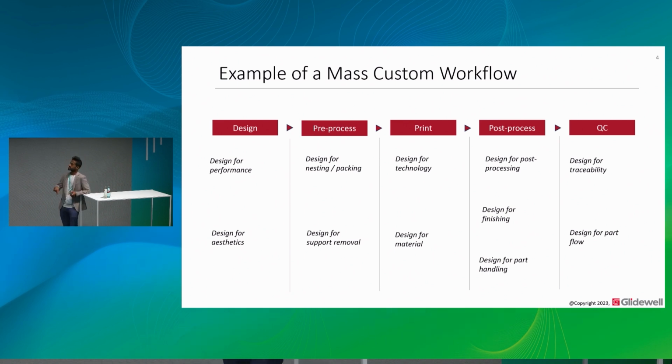So that means there's a separate finishing or polishing step that usually a skilled technician is going to do. They're going to have to eyeball things, and they've been trained over years and years. And there are design elements that we add for both of those separately that help improve that. So we're actually fine with increasing print time if it helps reduce finishing or post-processing time. For example, with the polishing or the finishing, we'll sacrifice a quicker print to print these night guards at a specific orientation, just so that we have better surface finish on some of these features, and the technicians can polish these a lot quicker.